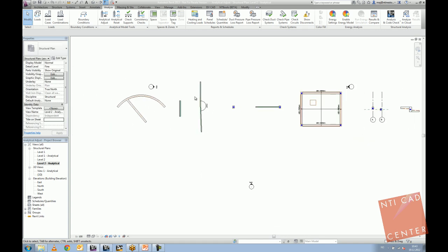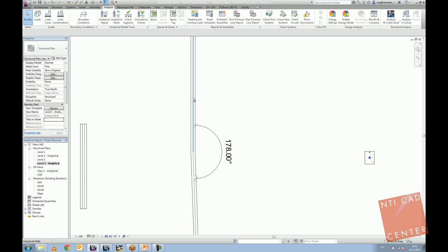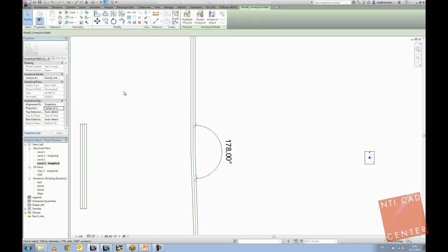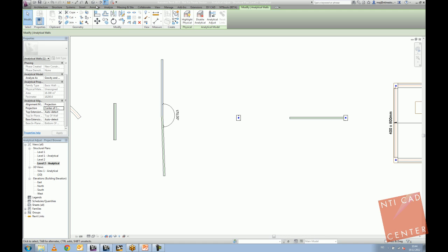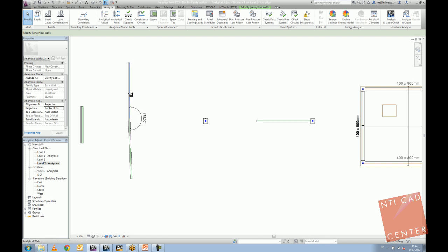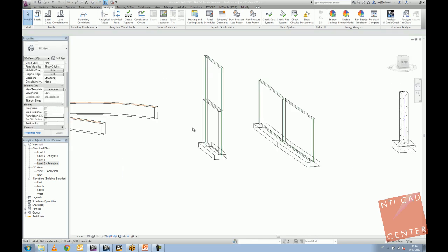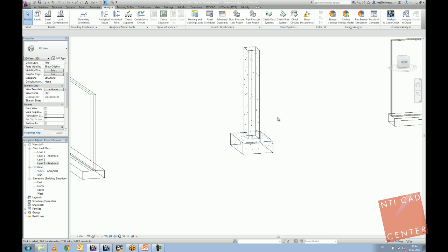Again, as moving, you will see that actually in most of the cases I'm using all of the properties. So that's again something I really want to stress, that you don't need to go to the part which I specified before, Analytical Adjust. You actually can do most of the modifications using the properties, and then once you do it through properties, you know that will always follow. So basically it will be updated.